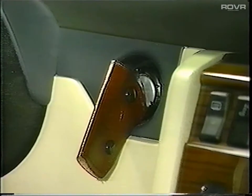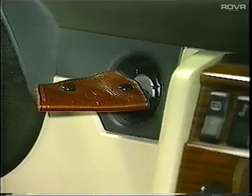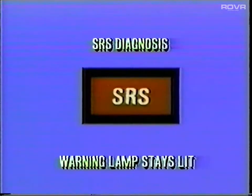When the ignition key is turned on, the SRS warning lamp in the instrument cluster illuminates for approximately 4 seconds while the control unit runs a test cycle. If the system is fully operational, the warning lamp goes out. A problem is present in the system if the SRS warning lamp does not light, or if the warning lamp stays lit. The cause can now be diagnosed by a blink impulse readout provided by the SRS warning lamp.